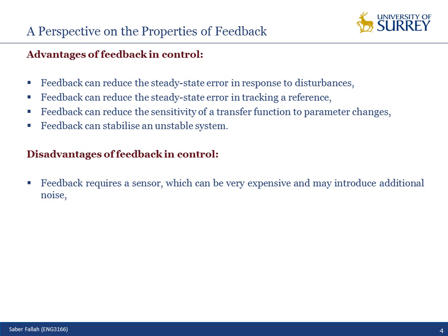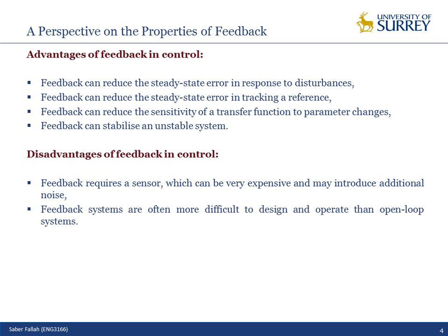But for a simple control system, you need at least one sensor to measure the output of the system, which adds some additional cost. And again, if you use the sensor, because they are very sensitive devices, they usually add some noise to the dynamics of the system, which adds complexity to the performance of the system. But we have many ways to deal with such issues, the noise issues. I will talk about the noise as well in this part of the lecture.